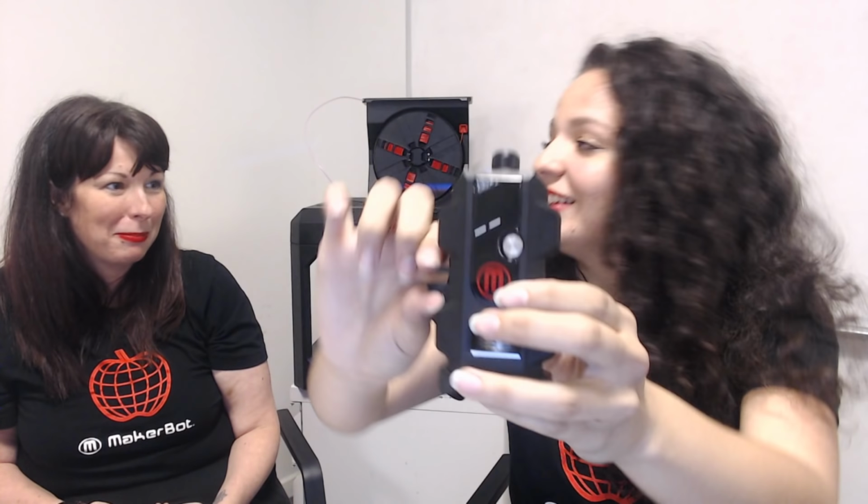These will help you when you're loading filament. It changed my life. This can improve and extend the lifespan of your extruder, but just pinch those 2 tabs when you're loading or unloading filament, or if you're having an issue loading filament, like if there's a jam or something like that.